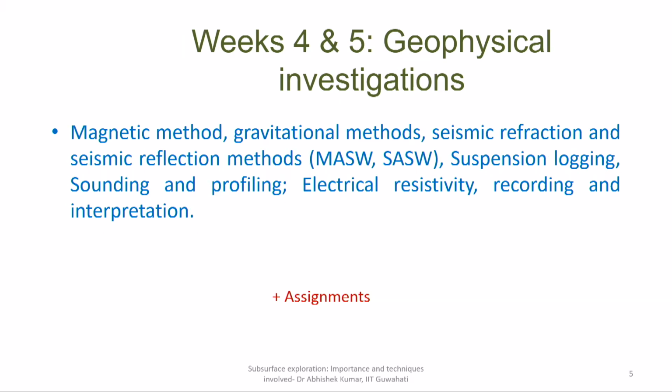Week 4 and week 5 we will be discussing more about geophysical investigation. In order to understand more about the subsurface and to get more information confidently within less time, geophysical investigations are also becoming popular nowadays. Some of the geophysical investigations involve magnetic methods, gravitational methods, mostly focused on understanding the subsoil and geological formations. Seismic refraction and seismic reflection surveys are nowadays very popular, so that we can quickly understand the strength characteristics of near surface material, both for static as well as dynamic loading conditions.